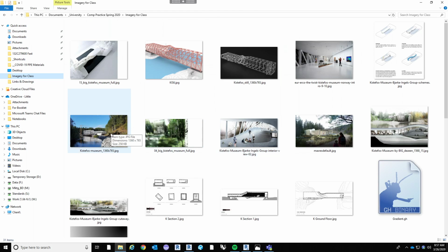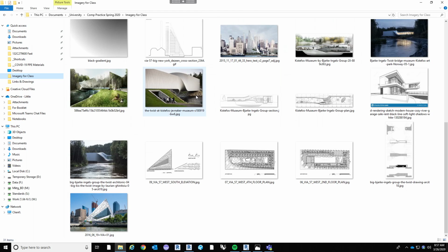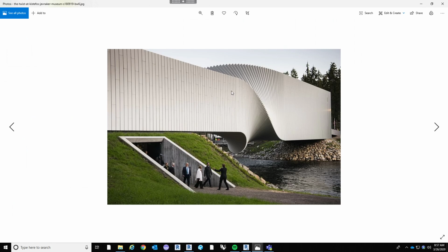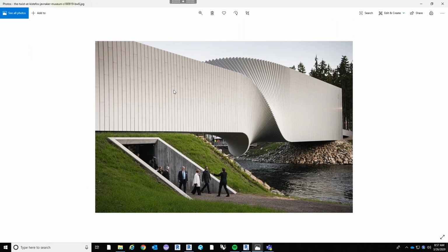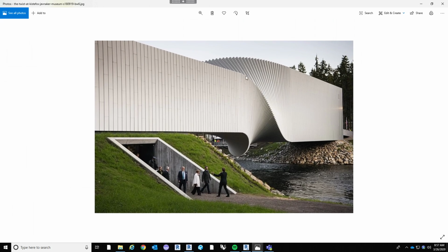So if we go to an exterior view, we can see that this skin is faceted, it's panelized, and to do that, we'll actually go in, and instead of having a smooth exterior skin that's from a true wall that's associated to a face, we'll go in and actually create a divided surface in the mask, and use that as our basis to create these facets.